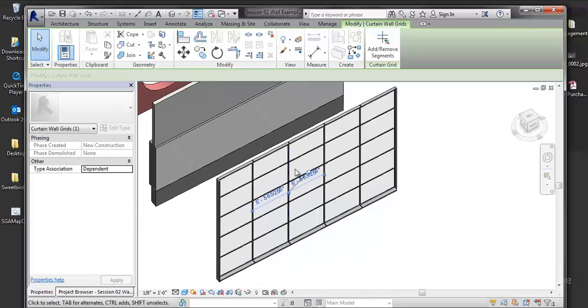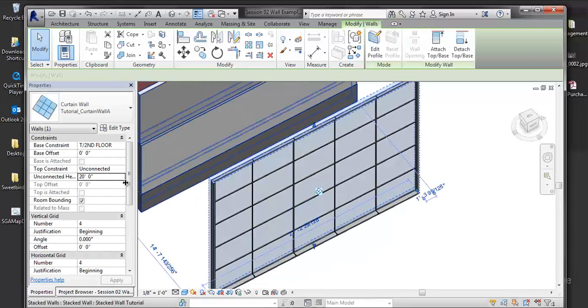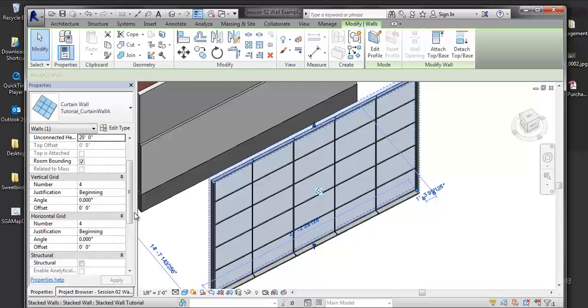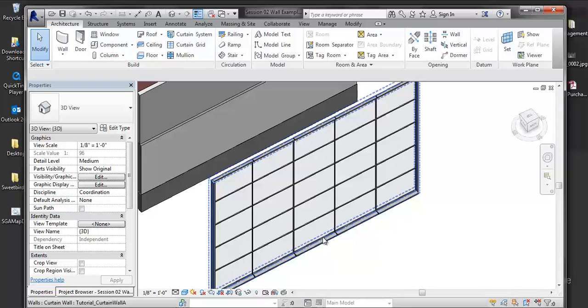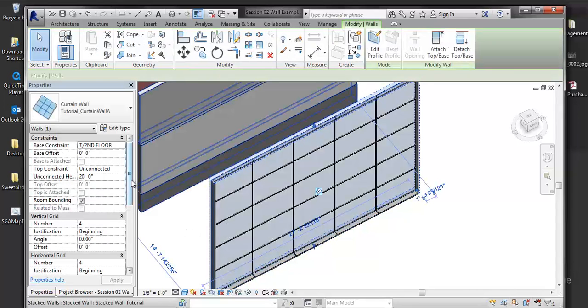So I think with the curtain wall, like Aaron said, we'll get into it a little bit later, because it is kind of just traveling down the rabbit hole, I'll call it, with how far you can go. So there's a lot of things happening within this assembly. One is you have the wall itself, then we're subdividing that wall, and then within those subdivisions we're loading profiles called mullions. They're sweeping those mullions, and then I'm also, within each one of those, loading in individual panels into that divided surface. So there's a lot going on within the curtain wall system itself. So it can be fairly complicated at face value.